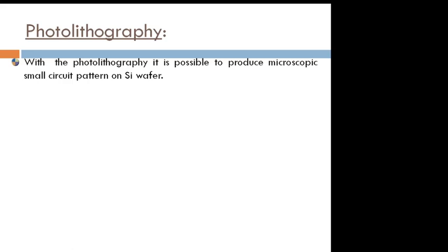Therefore, rather than doing the same circuit many times, a photographic technique should be developed, so that each segment of the IC is engraved or takes shape. That is why the photo technique is important here. It is used to execute a certain component on a certain region of an IC chip.